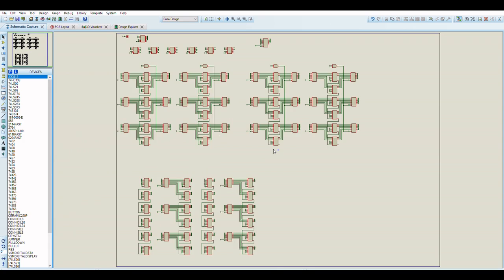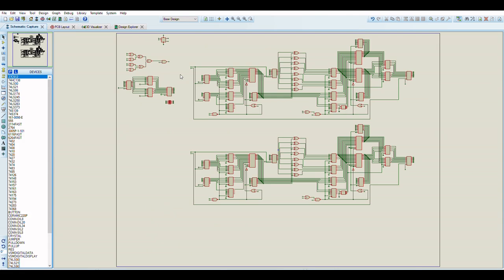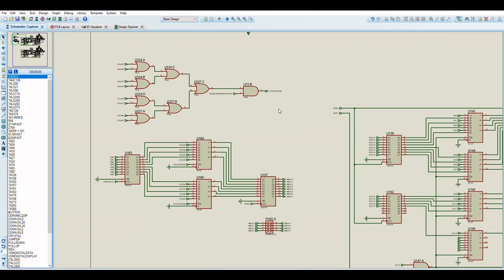So root sheet 10 contains the logic that's necessary to decide on, based on a pixel lookup value into this large tile screen, the tile definition it wants to read. Tile pixel data is actually stored on a byte per pixel basis.